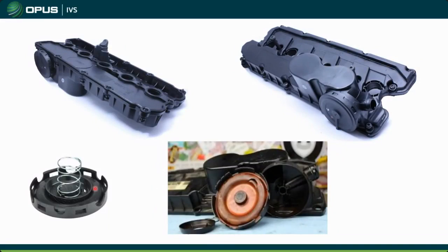The way that this pressure regulator works is with spring pressure on this diaphragm. As you can see here, this little port is actually an atmosphere vent, and that's used as a reference to atmospheric pressure. That's how it regulates the pressure. So, of course, if you have a tear in this diaphragm, you now have a vacuum leak where air sucks in.